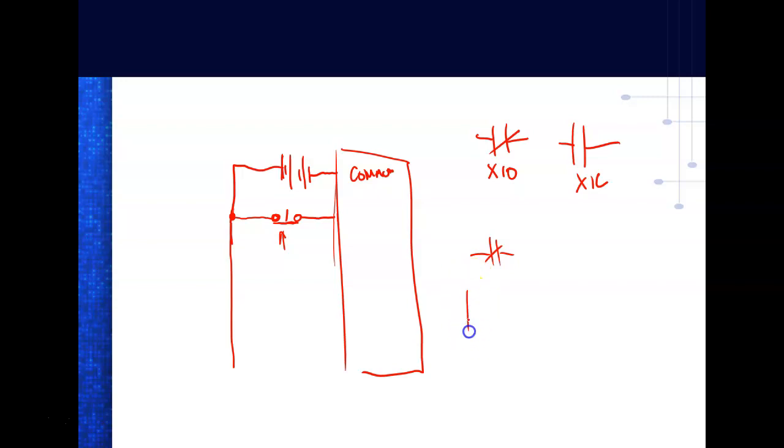The big problem is if I come over here like this. This is a standard, probably the most used circuit out there. I'm going to start off with this right here, and I'm going to label this stop. Then I'm going to come over here and have a normally open, and label this start. And then I'm going to come over here, and this is not program controllers, this is relay logic. I'm going to label this run. And I'm going to put a contact right here and label this run. I didn't do that good a job. People call this a memory circuit. They'll call it a sealing circuit. It's called a 3-wire circuit because it gets 3 wire numbers.